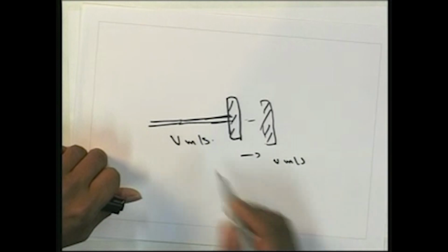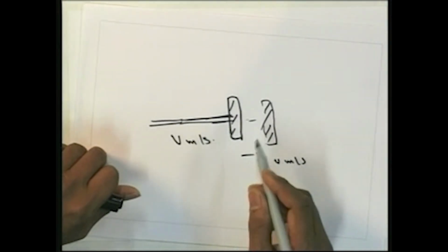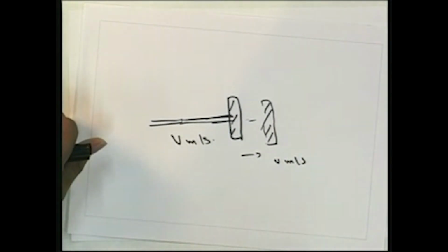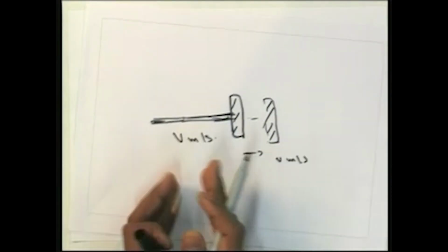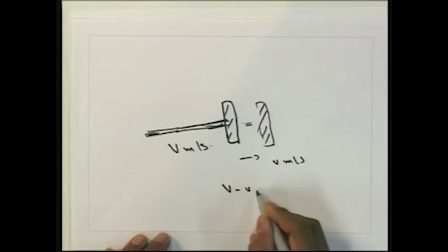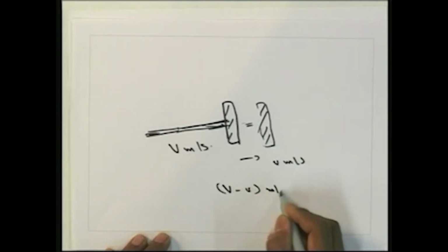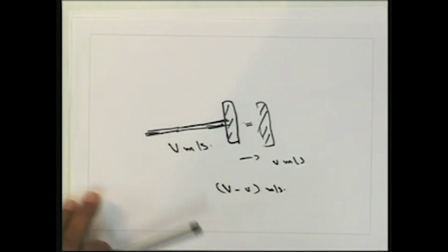Then we will be finding out the mass which really overtakes the plate per unit time. So, we have to consider the relative velocity, and what mass will be overtaking the plate per unit time when the plate or the vane is moving. Here we can see that capital V minus small v will be the relative velocity, and that will be used in the calculation.